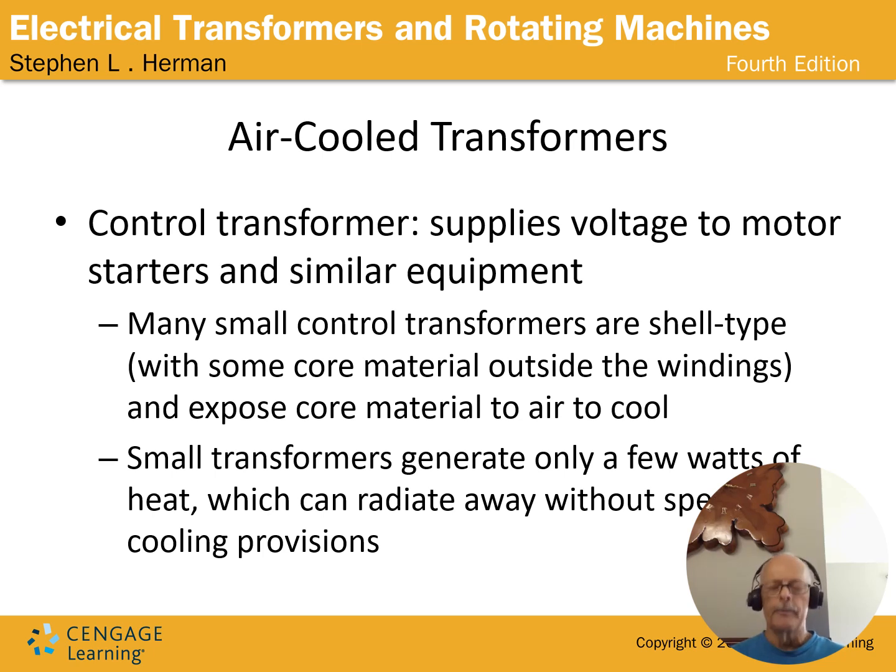That cooler air is then next to the transformer and begins to be heated, drawing heat away from the transformer. Once that heat begins to expand that air, it grows lighter and starts to rise, pulling in more cool air. You get this convection going on, and it will carry off the heat of the transformers.